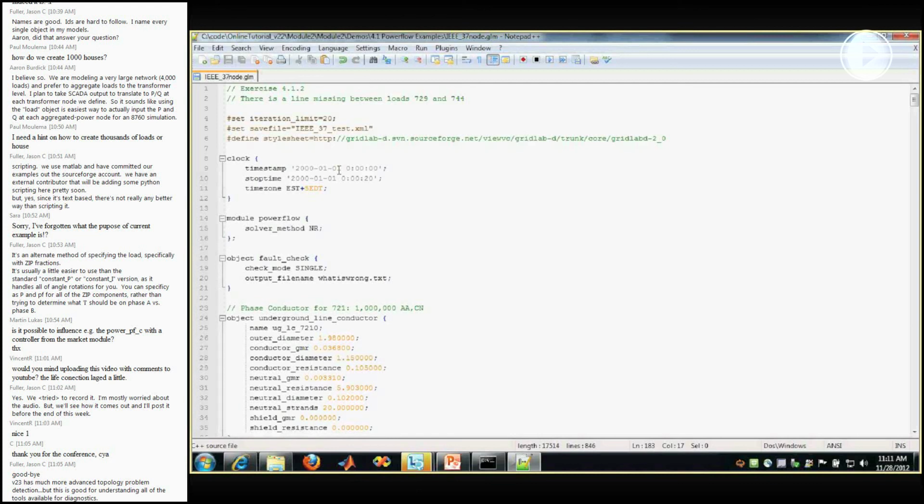That is an error right now in Newton-Raphson. Conceivably, we'll eventually get Newton-Raphson to work with islanded systems, so that may not be an error in the future. It may start giving you basically the same result backward sweep would, where it'll imply a second swing node, and you'll get two sets of answers, and unless you realize that you accidentally segmented your system, you'll get what looks like a valid answer. So just something to be aware of.